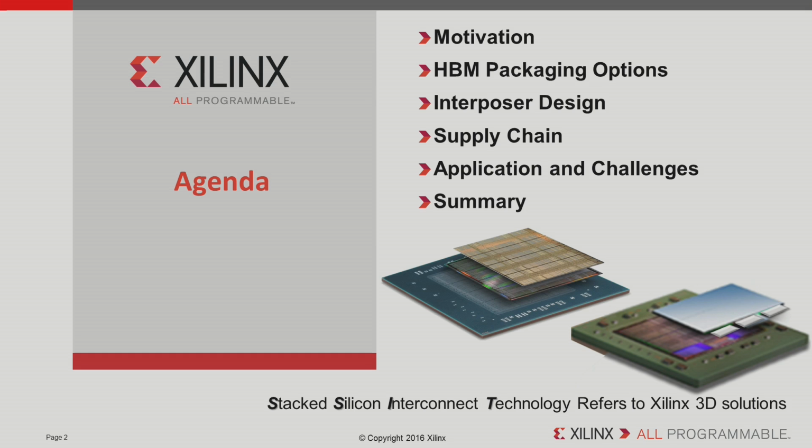So for FPGAs, one of the strong motivations for HBM usage is data center applications. So I will start off with how FPGAs play in this area as a motivating factor. And as some of our earlier speakers, I think Kevin, touched upon, there is a plethora of packaging options coming out depending upon whether the solution is coming from a foundry or a substrate provider or an assembly provider.